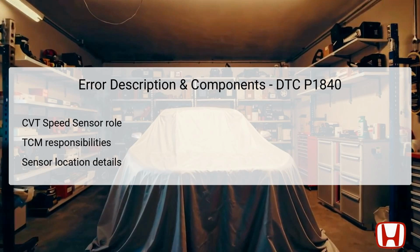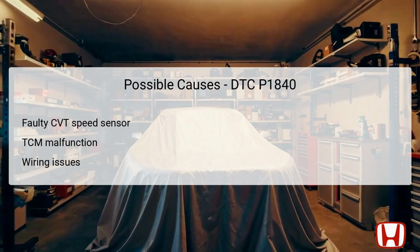The CVT speed sensor is typically located near the transmission assembly, often mounted directly on the transmission housing, while the TCM can be found in various positions depending on the vehicle model, commonly near the engine bay or within the cabin area. This physical relationship means that any failure or inconsistency in the sensor's performance directly impacts the TCM's operation, potentially triggering a DTC.